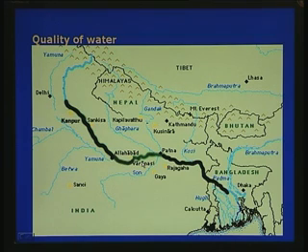By this slide I want to explain one more point. If you want to take raw water for supply from, for example, Haridwar, we have very good raw water quality, and hence the treatment that should be given will be less, and the cost of treatment also will be less. As you pick up heavily polluted water, the pollution is more, and hence the treatment has to be more extensive, and the cost of treatment will be more. So, all along the river, at cities like Kanpur, Allahabad, Varanasi, Patna, the treatment has to be more extensive than what can be given at Haridwar. These are some of the aspects we would like to say on the quality of the river.